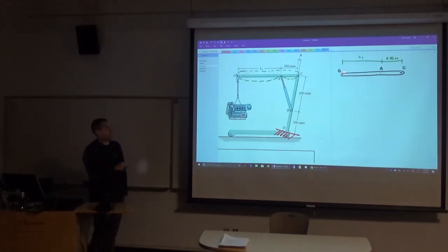Like, what's happening at G? How about that? Force in the negative y direction. Yeah, and that force is due to the weight of this motor right here. So technically speaking, we could include like a chain going down on the center of mass, but with a quick section cut, we can tell the tension in this cable simply has to be equal to the weight right here.